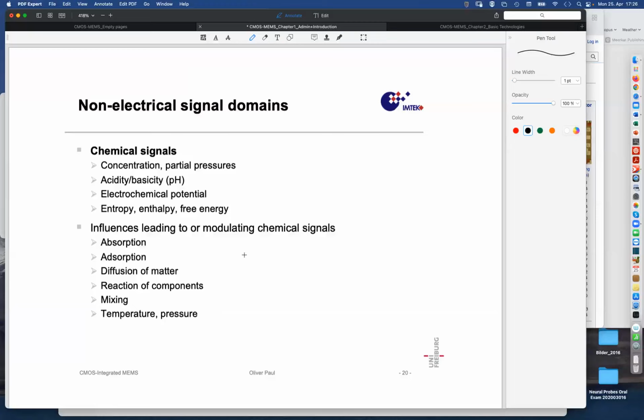But there are also other chemical sensors, like, for instance, those of Sensirion. They have volatile organic compound sensors. So the more complex molecules that are now filling this room. Some sweat components have the smell. Yeah, these are so-called volatile organic compounds. And if you want to measure the quality of air, if you're able to measure those compounds, then you can say, okay, now is the moment to switch on the air conditioning, to give the people a good breathing again.